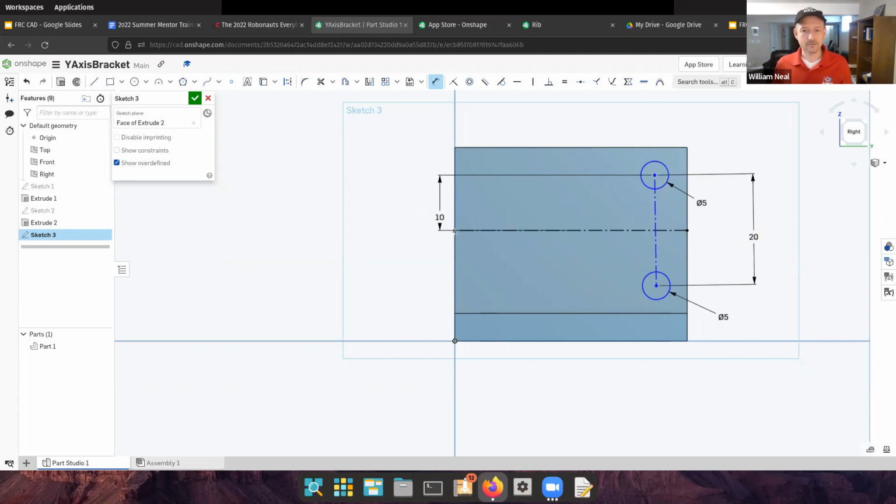And that center line was hopefully on the halfway points that naturally come up when I'm making these little constructions. You see the midpoint just appears, so I can create these constructions at strategic points along my objects. The final thing I may want to do is constrain them vertically. So I will take this. Now it's not a construction, that's fine. Hold down Shift as I click these 2 points and make this 0.